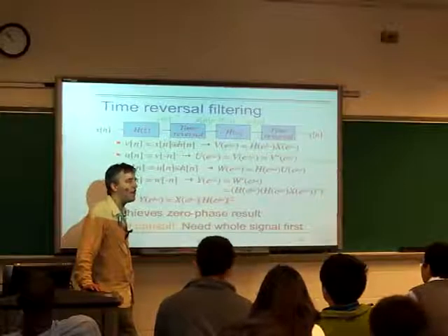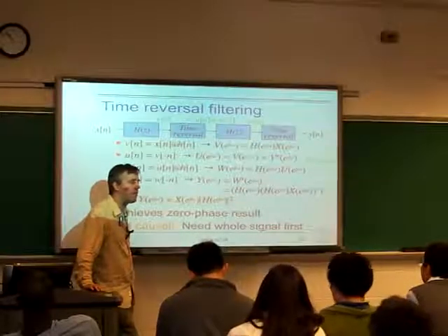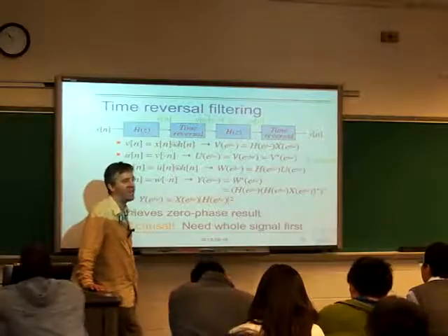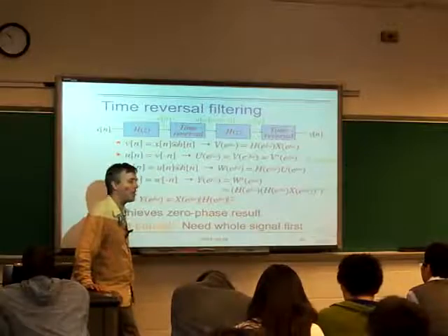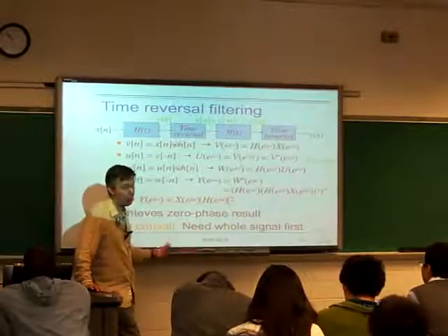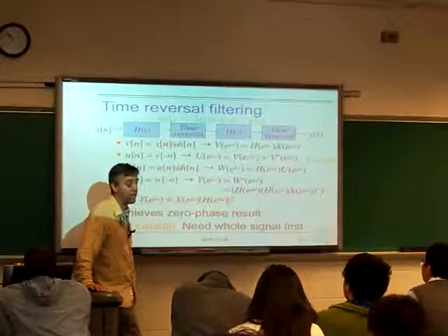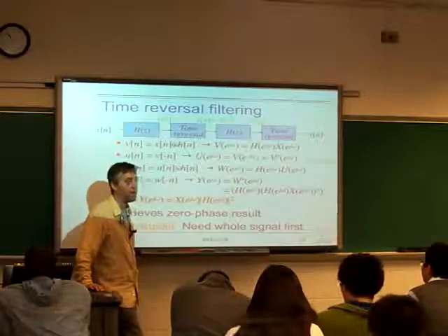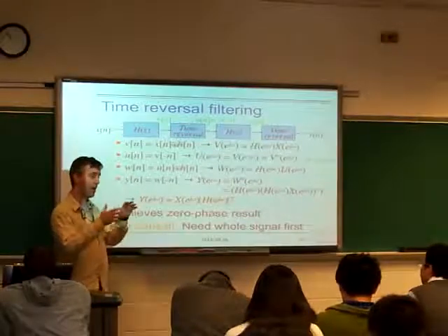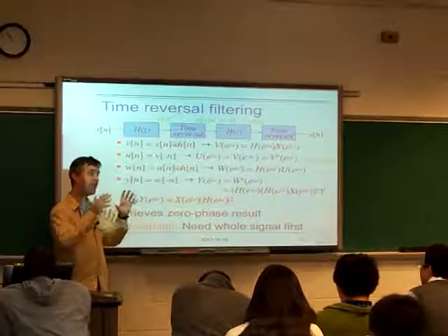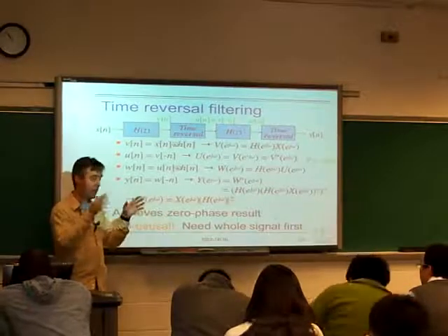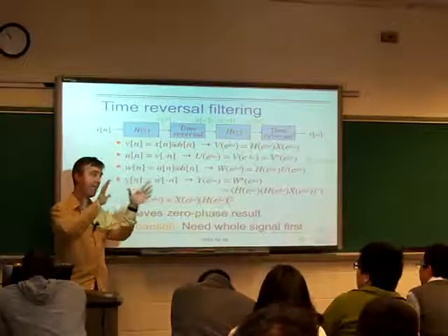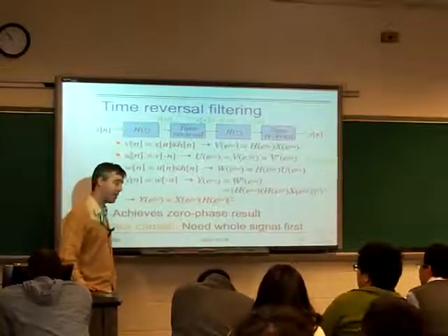The situations in which you have complex frequency responses, you have to mean something by that, right? In general, we introduced the imaginary axis just as a mathematical convenience so we could use complex arithmetic, not because it had any meaning in terms of the original signal. Now, sometimes you can imagine complex signals, particularly in high frequency signals where you're talking about a component around some carrier, and so it has an in phase and a quadrature term.